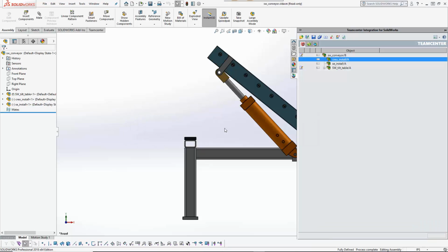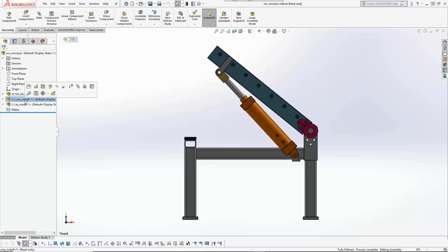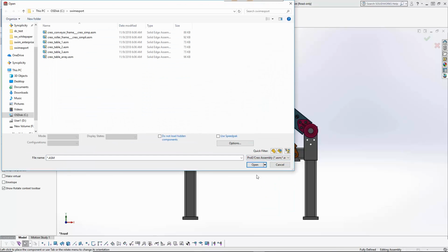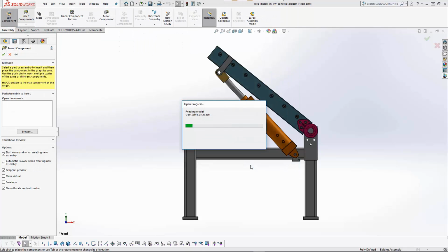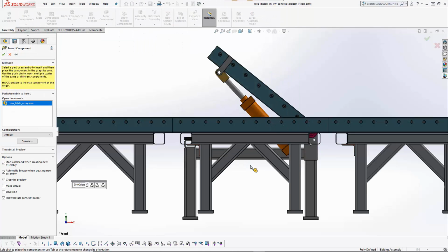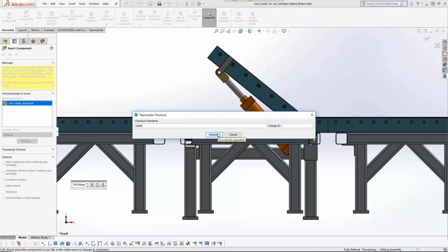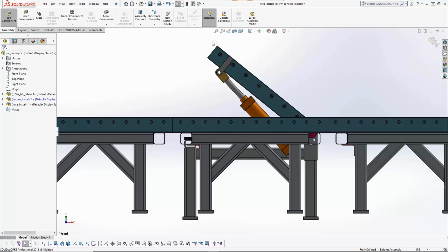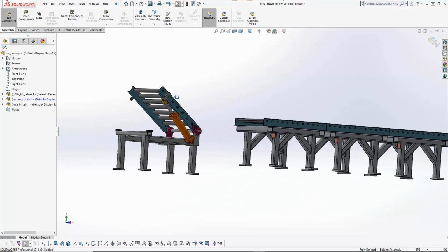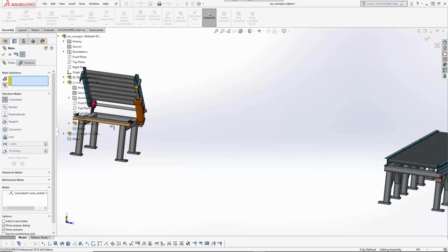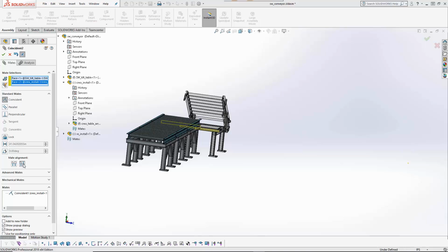Once the Creo assembly and its components are retrieved from Teamcenter, the user is advised to insert the assembly using standalone SolidWorks functionality, due to a SolidWorks API limitation. In the future this step will be performed automatically by the Teamcenter integration. The Creo subassembly is now positioned within the SolidWorks assembly, using mating constraints. These constraints will be retained as the Creo design is changed in its authoring tool.